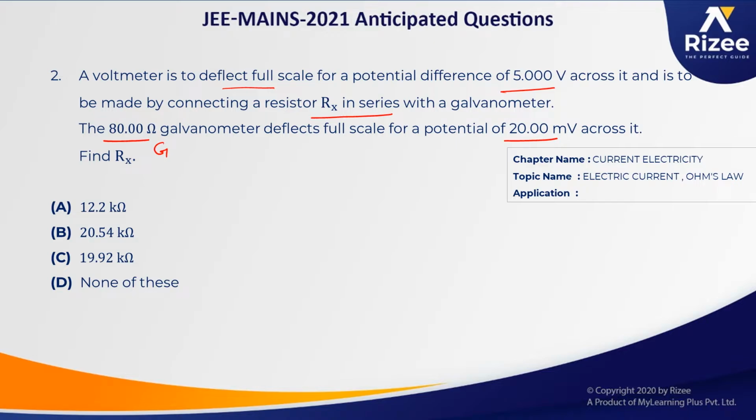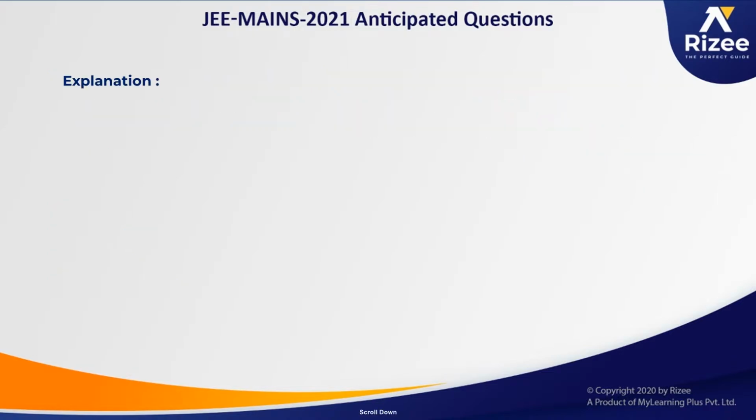So this is the question which is concerned with current electricity, and in this one, conversion of the galvanometer into an ammeter conditions. So how to solve this particular case? In this case, this is already a voltmeter which is measuring, giving certain values to it. So from this one you can find the current passing through it, because you are going to connect another resistance in series, which should not change the value of the current passing through that one.